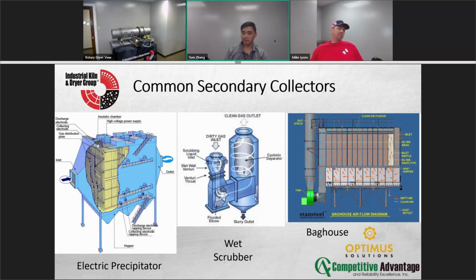But I know one thing: you definitely don't want to be on the end of changing out bags. That reminds me, remember when I said overflighting? When you overflight, you can lower the exhaust gas temp. If that is too low and you got a lot of water, you will do what we call mudding the baghouse. I have not done the change, but I have never heard anyone that enjoys changing those.